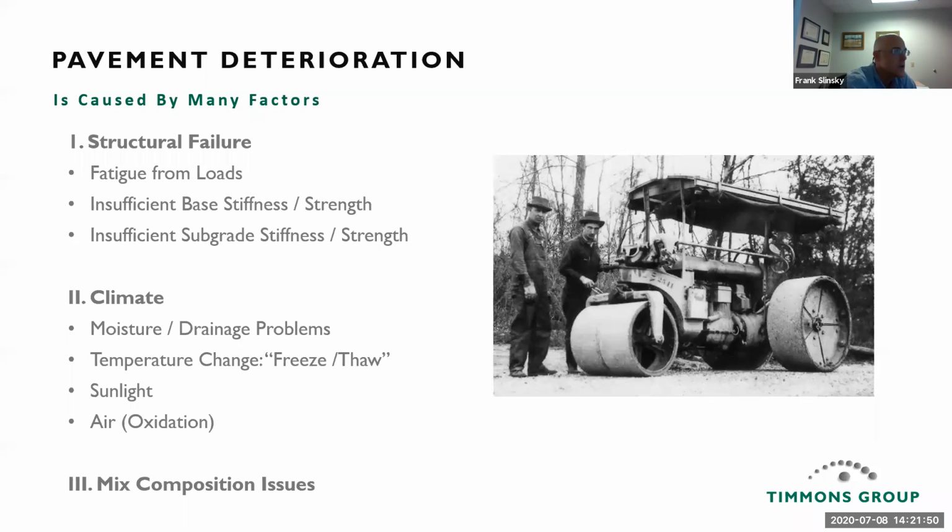Pavement deterioration is caused by many factors: structural failure, fatigue from loads, insufficient base stiffness or strength, insufficient subgrade stiffness or strength, climate, moisture, drainage problems, temperature change, freeze, thaw, sunlight, air, oxidation, or it could be mixed composition issues.